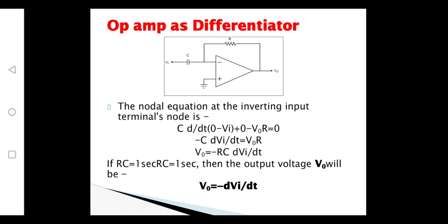If we want to prove how the op-amp can be used to reject low frequency components and pass high frequency components, we need to write this output voltage in terms of phasor equivalence. That is, by using a Laplace transform, we represent this complete time domain equation in the S domain, or Laplace domain, and replace S with j omega.